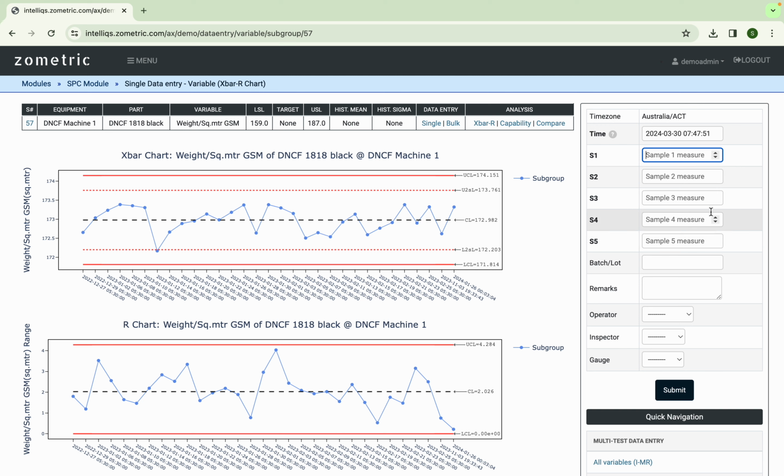This not only helps organize my control charts and SPC program, it also reduces the need for training the operators, because somebody sitting centrally can configure all these subgroup sizes and the sampling frequencies, and the operator on the shop floor just has to follow the standard that has already been set in the software.